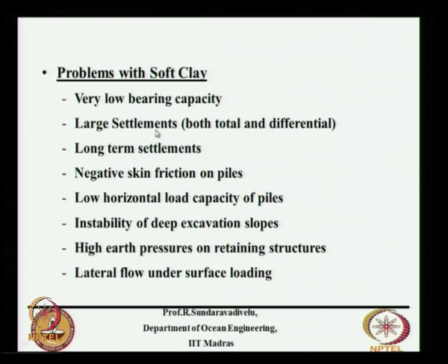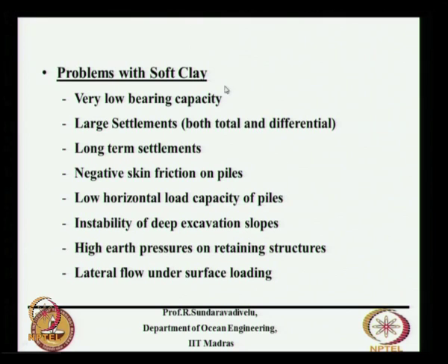The settlement is about 3 meters. Once you put the breakwater stone, if you do not treat the soft clay, then the settlement is about 3 meters where the height of the breakwater is high, and at other ends it will be less, about half a meter. That means the total settlement is about 3 meters and the differential settlement is about 2.5 meters.